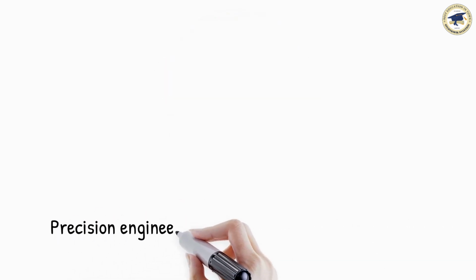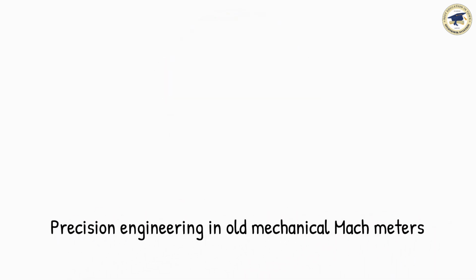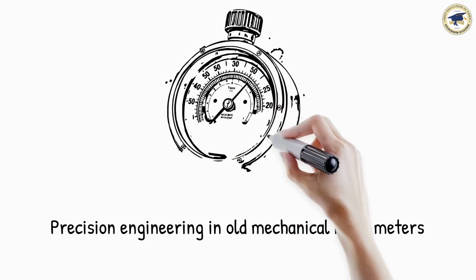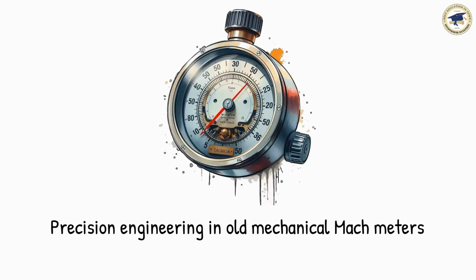In older, purely mechanical instruments, this system required very precise engineering. The capsules had to be thin enough to expand under small pressure changes, yet strong enough to withstand repeated cycles. Any friction or backlash in the gears could introduce errors. That's why regular calibration was necessary.